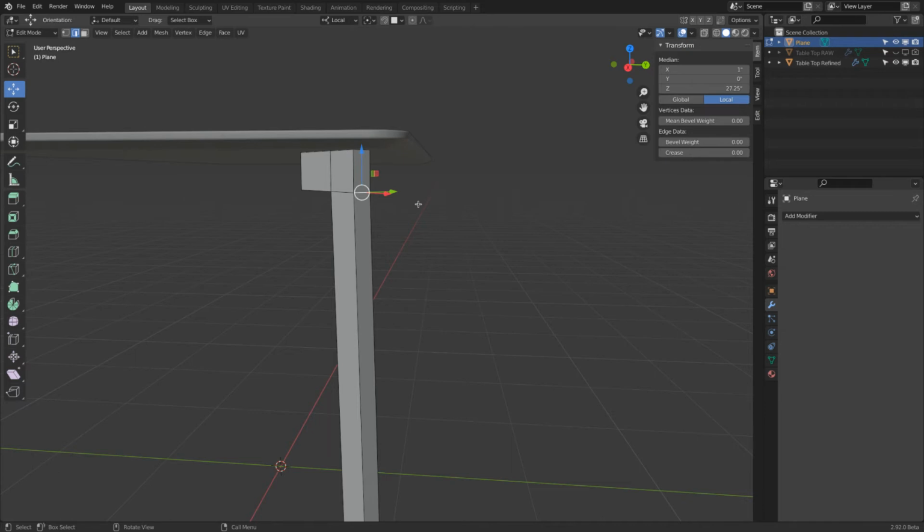Very easy. We select this edge, then we go and turn this on. This is auto merge. What does auto merge mean? So when I press GG, not one time G, but twice G, and I move my mouse up and down, you see how I'm sliding the edge. And when I continue to this corner, it stops, actually, I can't slide anymore.